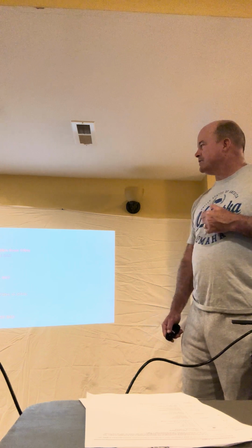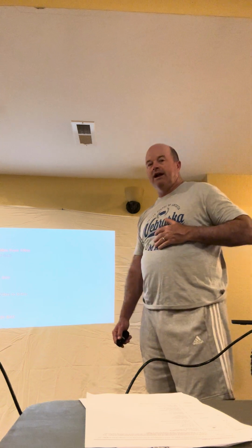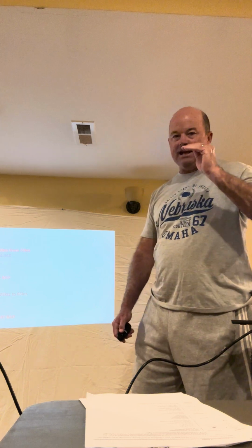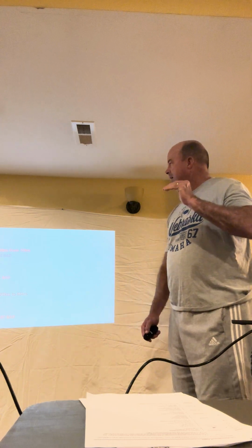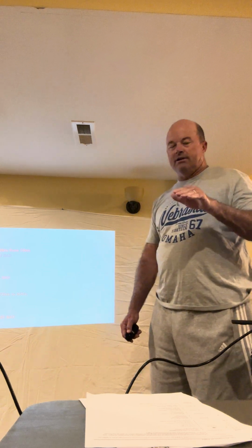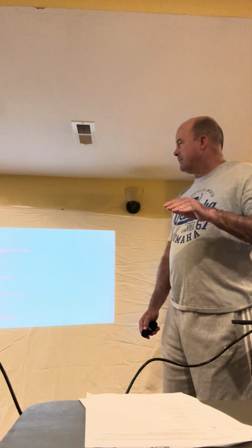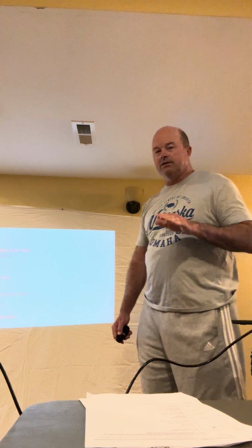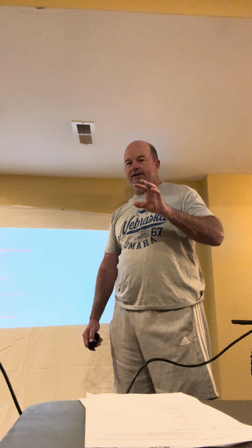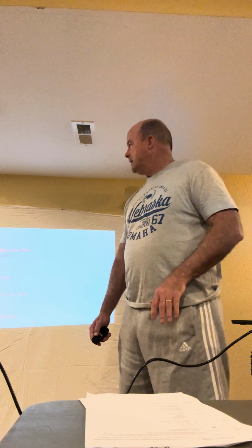What happens is stall speed increases. So this is bad, right? So you're going to stall at a higher speed, right? As opposed to 72 knots, you're going to stall at 80 knots. So this is bad, right? The nose points down, right? So it goes down, and you might think, well, that's pretty cool, but yeah, it's all right. But you've got a slower airplane, right? Because it's inefficient, because you've got the tail creating more drag. It's actually designed to have the nose up.